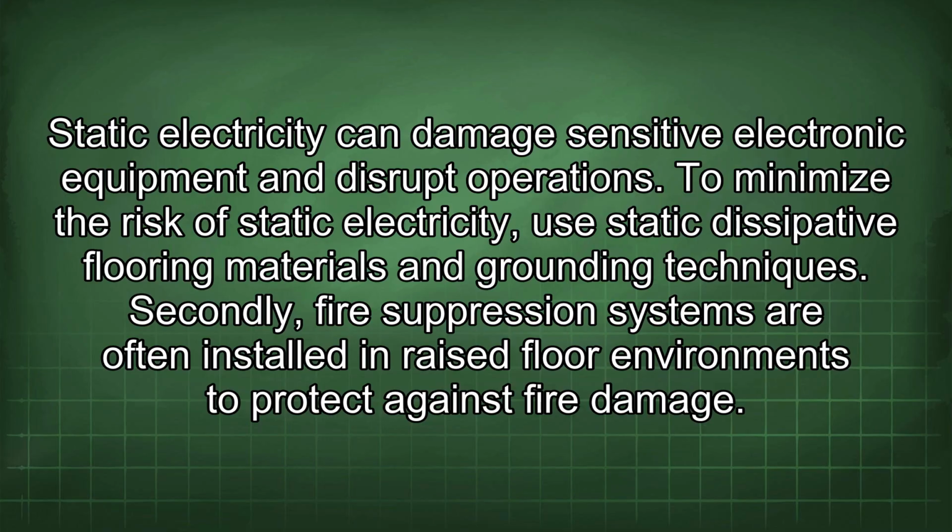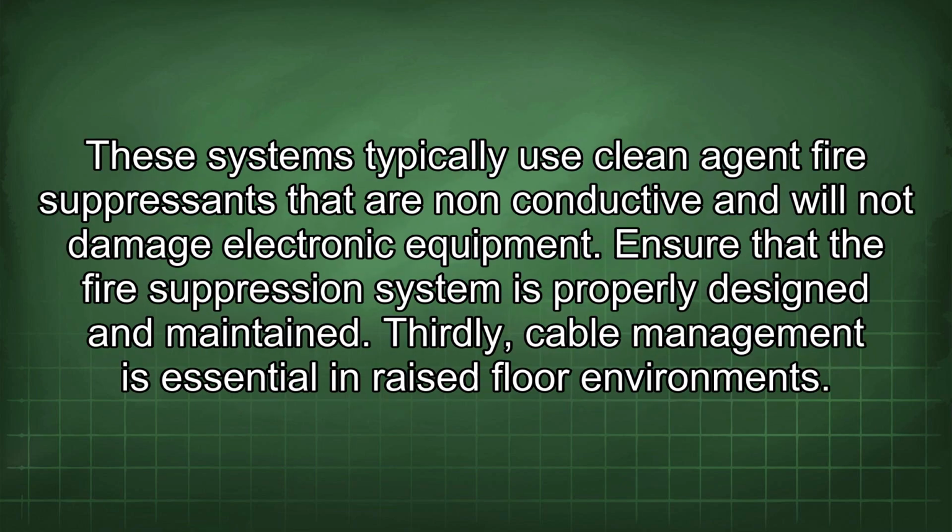Secondly, fire suppression systems are often installed in raised floor environments to protect against fire damage. These systems typically use clean agent fire suppressants that are non-conductive and will not damage electronic equipment. Ensure that the fire suppression system is properly designed and maintained.